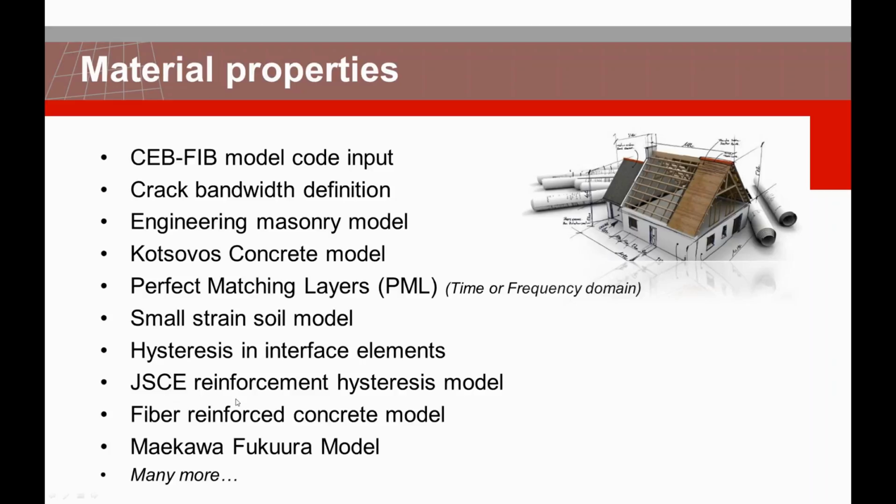We extended our embedded reinforcement material properties based on the Japanese model code, which deals with hysteresis material behavior similar to what we already have as Menegotto-Pinto, Monti-Nuti, and Dodd-Restrepo. We have also done other enhancements in the concrete field, such as extending the performance for fiber reinforced concrete, either steel or synthetic. There is also a great improvement and enhancement for the Maekawa-Fukuura model with certain verification documents, which I will explain, and many more.